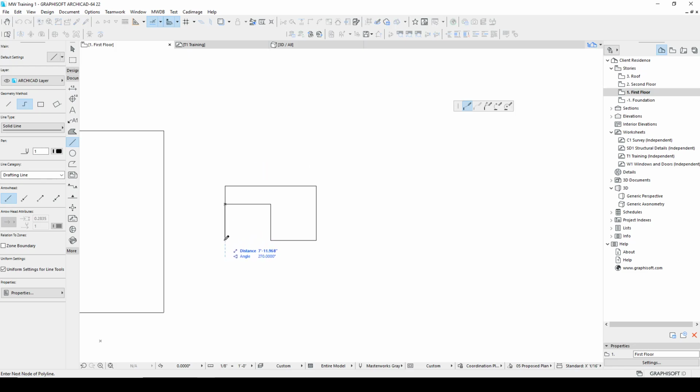And for instance, I can come down here and I can line this up. Once I let that come around, it's going to say like that, but you see that's a little slow. The alternative method, and I'll use Control Z, another shortcut that's pretty common, to remove the line. And if I hold Shift and I lock in that angle, now I can click this point and I drew a line to here, and I don't have to wait for the guidelines. I don't have to wait to slowly move my mouse back. So holding the Shift can be a little bit more robust and a little bit faster.